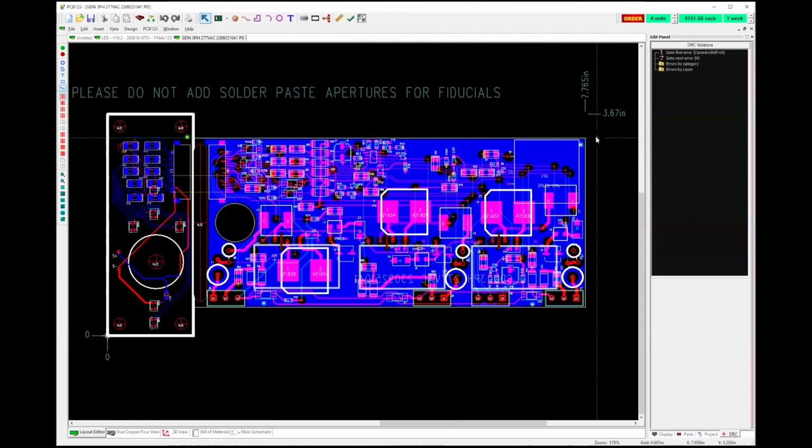Okay, so here's one. If, for example, I place a footprint for a DIL socket, the BOM does not reflect the price of the expensive processor chip it should hold. Is there a way around that? Yes, you have to either make the part using the correct DigiKey information, or you can have Snap EDA make it for you and use that part. If you just place the footprint on the board, it won't have any part number information.